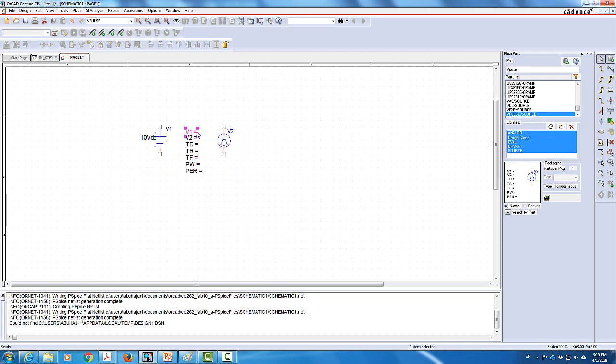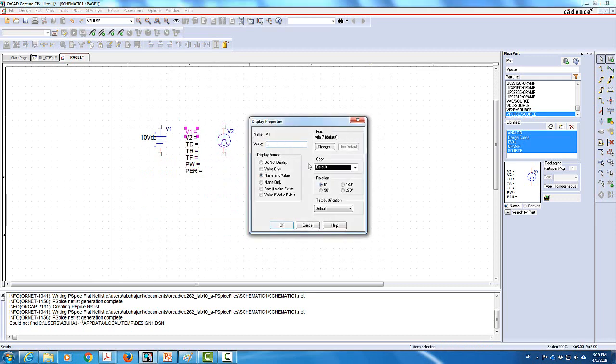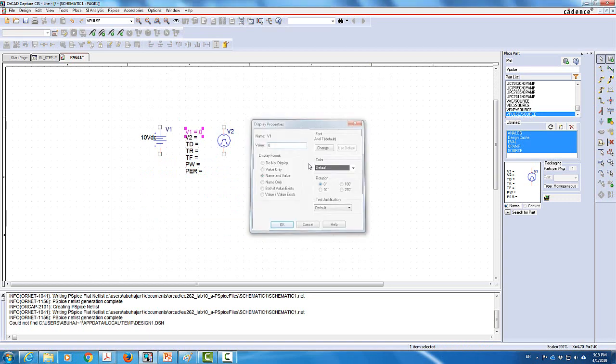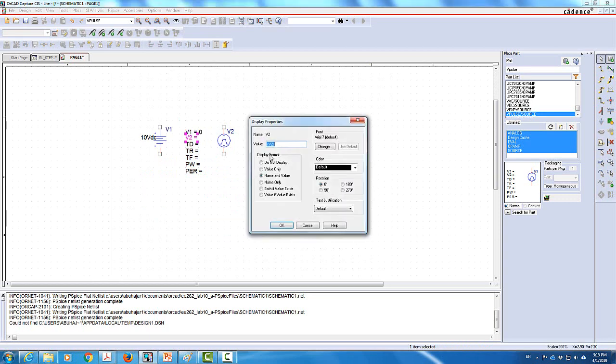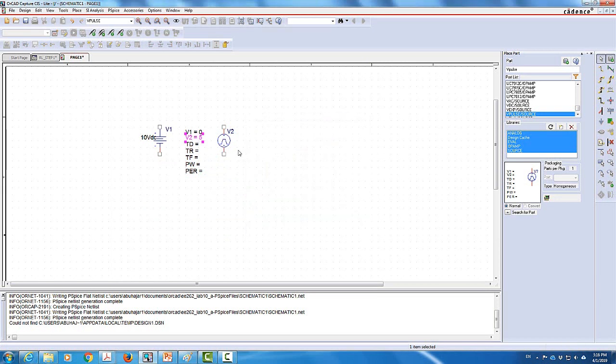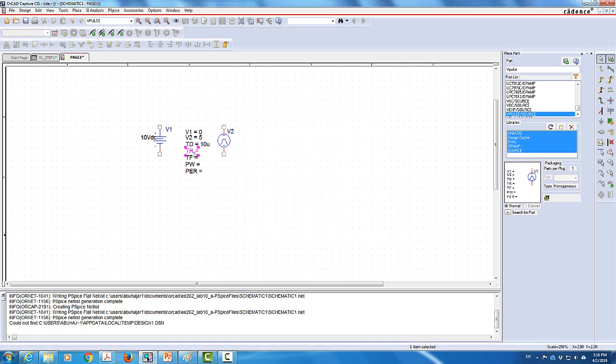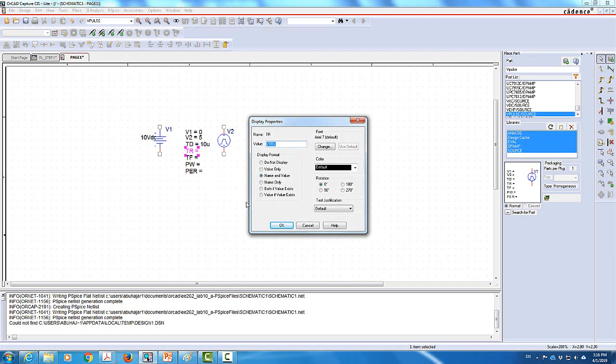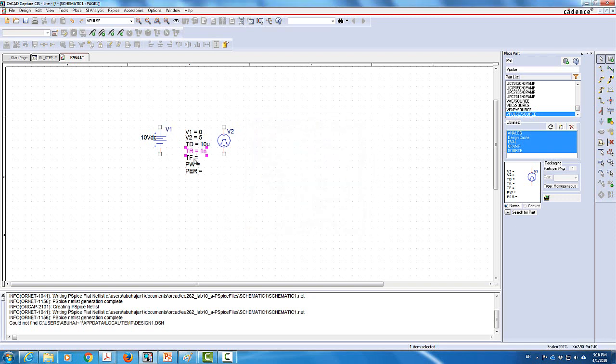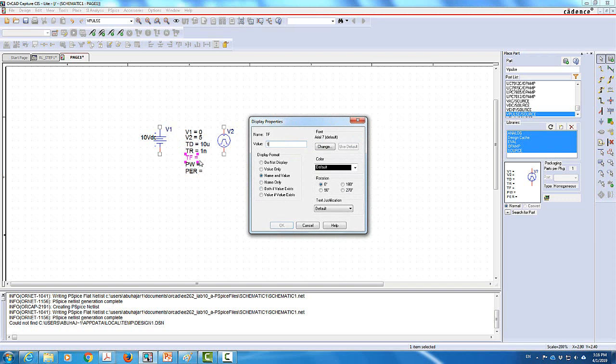So the switch was 0 before switching, so we're going to say that V1 equals 0. And then it became 5 volts. Then we're going to say that V2 will equal 5 volts. I'm going to start the simulation after 10 microseconds. This pulse is very fast, so it will take 1 nanosecond for time rise, 1 nanosecond for time fall.